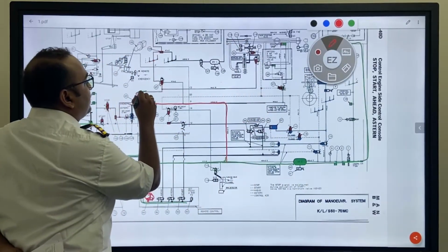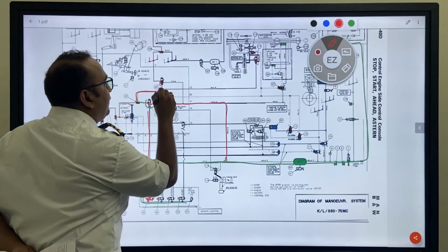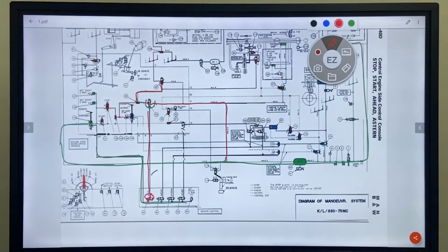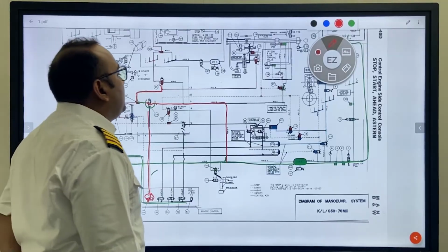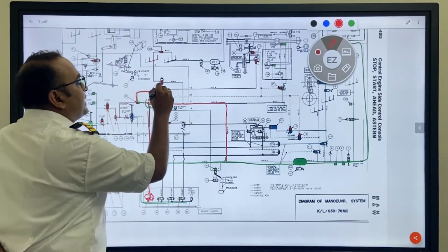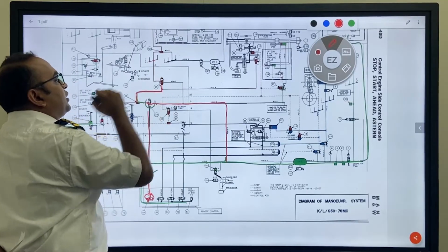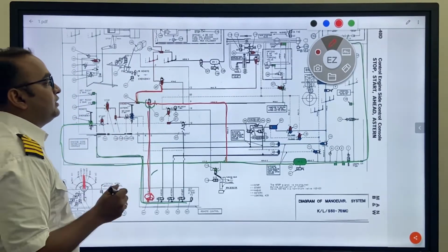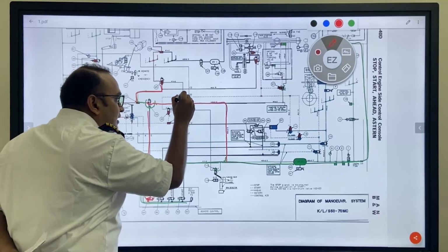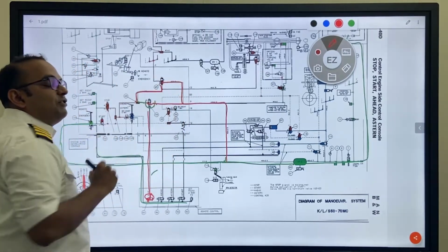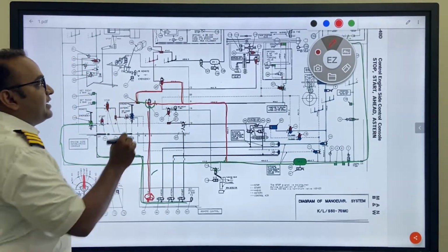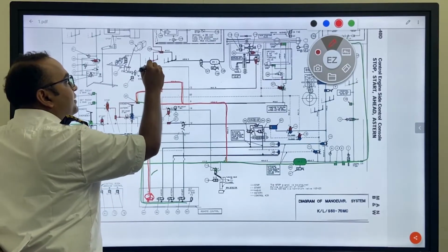It went up and has activated again a valve number 25. It is again a direction control valve, 2 position 3-way valve, and it has activated 25. This means the right hand side air can go on the left hand side. And what is on the right hand side? Again a branch from the control layer which was waiting, right? So now it can go up.